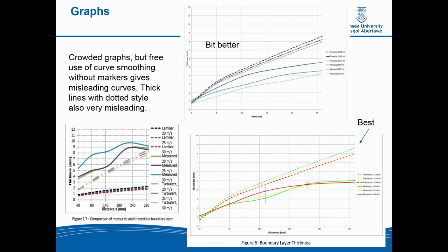It's actually fitting a curve unrealistically onto your data. That can lead to problems, because you'll start to interpret it as being possibly correct. You're going to start to think, oh, that looks like a nice smooth transition from laminar to turbulent, that must be right. And it's actually, well, no. There's a lot of things on the line that could be wrong. The datum could be wrong. So your transition point could be plus or minus 20% on either side of the point, and it just happens to pass through it.